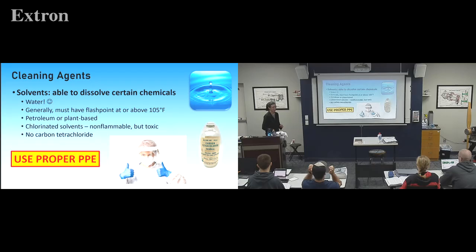So, it will kill you. So don't weld on something you just cleaned with fluorinated brake cleaner. Correct. Let's not do that. I don't know if you've heard of household cleaners, like never ever mix bleach and ammonia, because that will turn into a chlorinated solvent. And there's stories of people cleaning a bathroom, something's really dirty, and they put those together and they die. Don't do that.